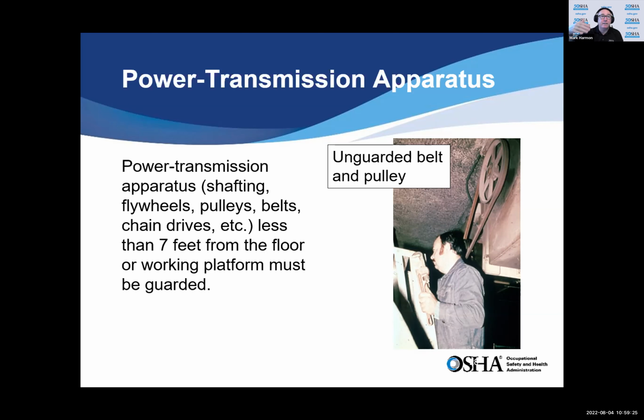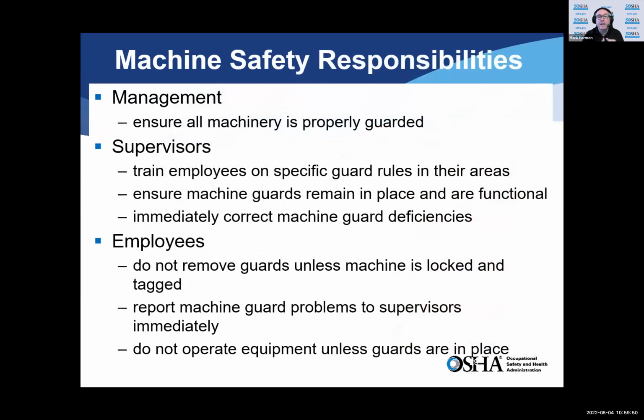So again, is it within reach, right? 7 feet, I can hold my arm up and I can touch 7 feet. So if it's the belts, the pulleys, chain drives, yeah, all these fall into 219, the OSHA standard for guarding, and must be protected so as to prevent someone from connecting.